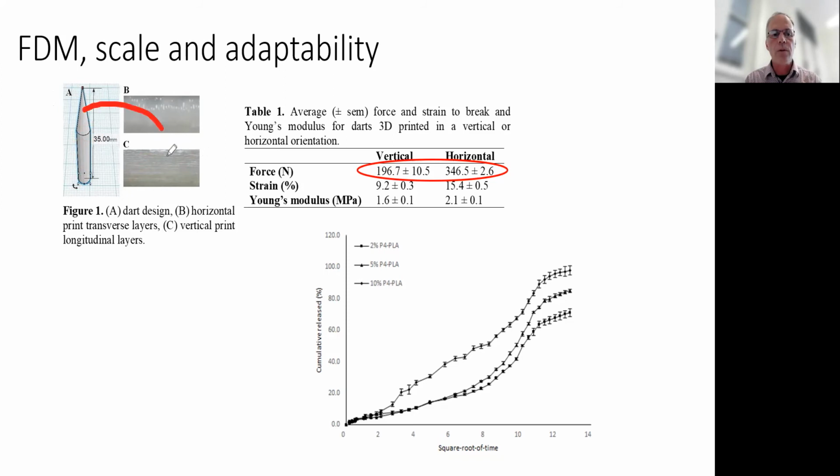If this dart was laying horizontal, 90 degrees, then when you turn it upright again, you'll see layers going across, and you can have layers going this way. Layer orientation then influences how strong the thing is that you have printed. Where your layers are your weak points, to be honest.